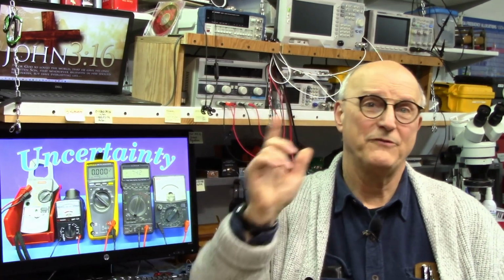Now, as I mentioned before, this isn't all about multimeters. This loading effect is a fact with any measuring device. In recent experience, a fellow engineer was measuring a voltage on a place in the circuit using his oscilloscope. He was wondering why the voltage was so very low. The problem was that this particular spot had an output impedance of 750 ohms, and he was using a 1 megohm input impedance oscilloscope with a 1 times probe.